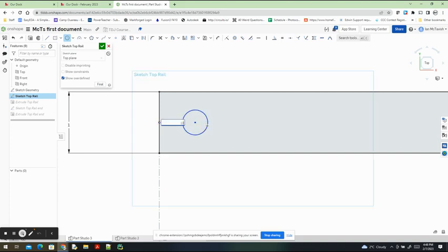Now, 13/64. So 13/64 inches is what we're going to use. And we're using it because the type of machine screw that we're going to use, that's the perfect size. That's a pretty standard size that we use frequently. So there's my circle. It's blue because it's not fully constrained. I can't move it up and down at all, but I can move it sideways.